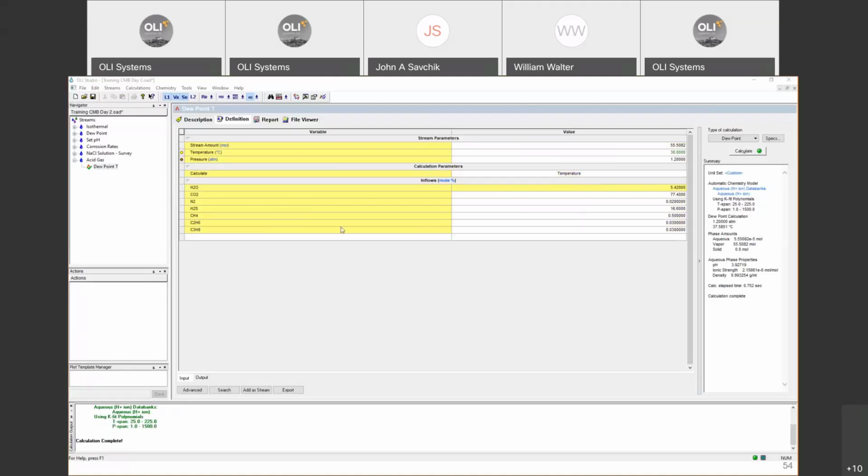Okay, so now you have to the right that the dew point temperature is 37.6. It's not far away from this 38 value. So really, a slight change in the temperature of the tubing, that is 0.4 degrees C, will cause a condensation. So we are at a high risk of corrosion there, okay? So we will need to increase the temperature of the pipeline to avoid any condensation, or we could neutralize, or we could simply change the alloy. Okay, but we don't know how the alloys are reacting to this composition of acid gases. So that's what we are going to find out. We're going to find out which alloy is the most resistant for this environment.